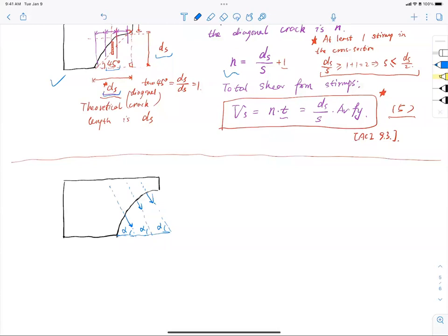So let's just connect them together so you don't confuse yourself. This is the angle alpha right here. So if this is the case, the shear resistance is the purple color back again, Vs. And mind you that this is inclined, not vertical anymore, and it has to equal Av fyt, the shear contribution from each stirrup, multiplied by ds over s, depth over spacing, and then multiplied by an angle-related function, that is sine alpha plus cosine alpha.